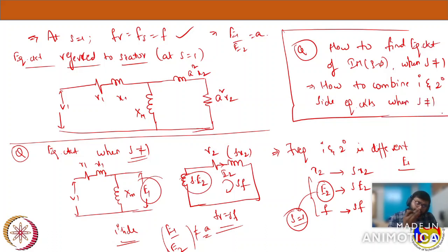Now let's try to understand. Let's say our motor is operating with some slip S, and also our rotor current is some I2 value. We can get the value of I2 current operating at the slip frequency. If you are seeing this rotor circuit here, right? To calculate the I2 here, what is the formula using KVL? Can anyone say what is the value of I2 here? You have the voltage and you have the impedance. What's the value of I2, the RMS value of rotor current?